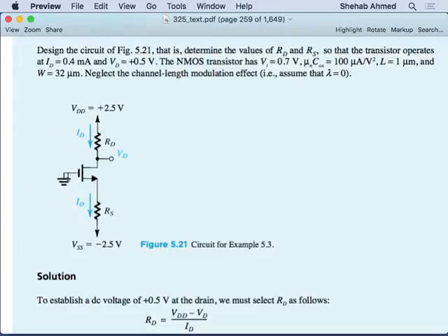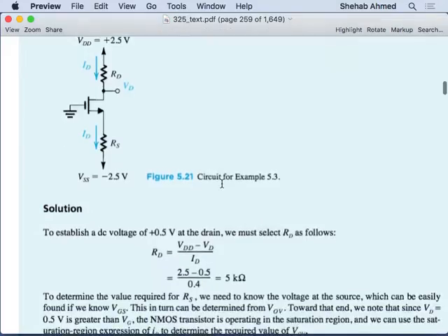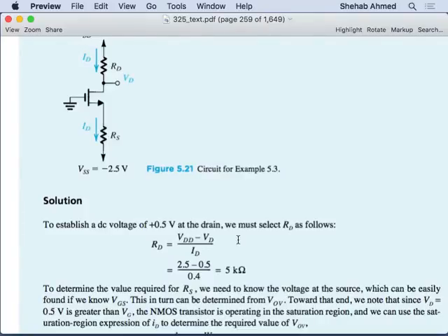We were given a voltage with respect to the gate, and then we had a circuit. This circuit defined the value of the source voltage with respect to minus 2.5, and the drain voltage with respect to minus 2.5, or with respect to ground, sorry, it doesn't matter. So this circuit that we added is what defined them. If I change RD, is it going to change the values that we got yesterday? Yes, it will. Didn't we add RD to control the voltage? Yes, you added RD to control the value of the drain voltage and the source voltage.